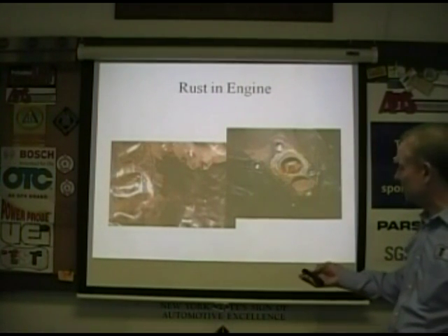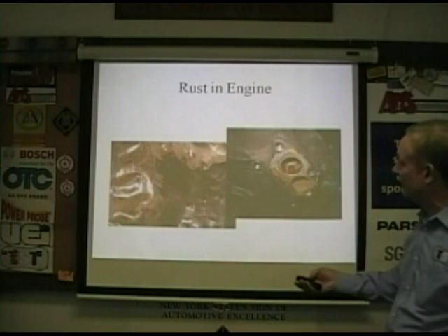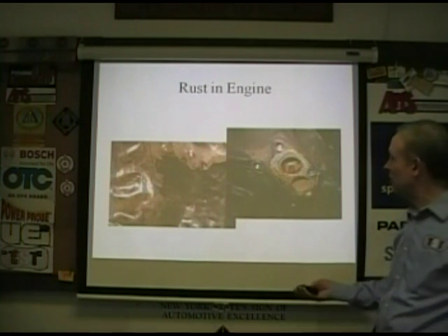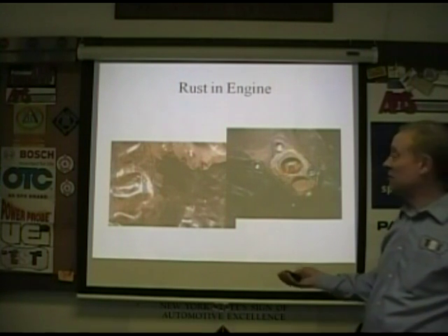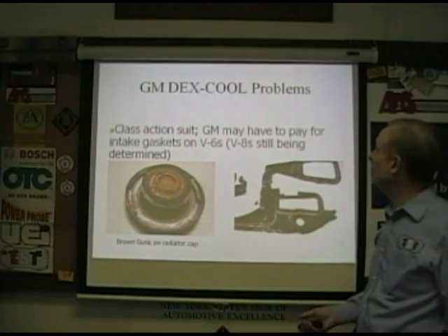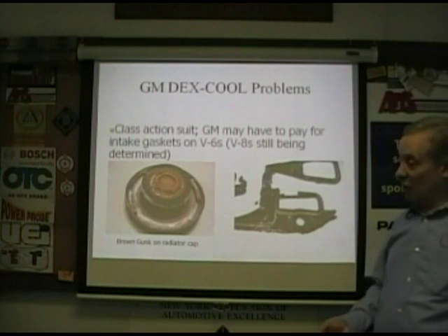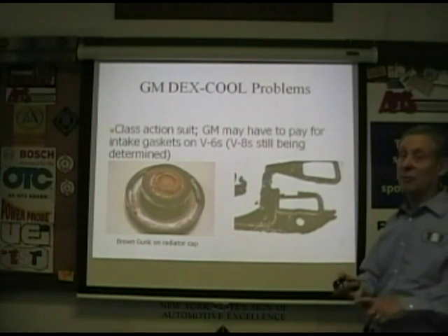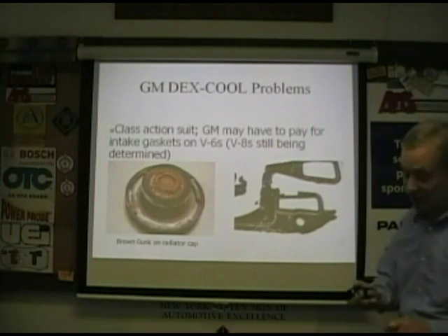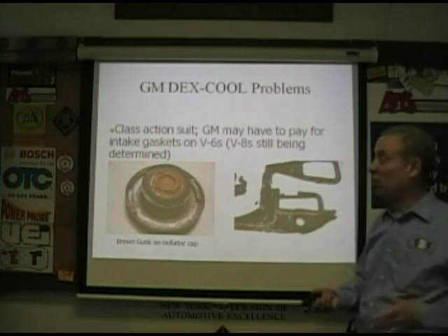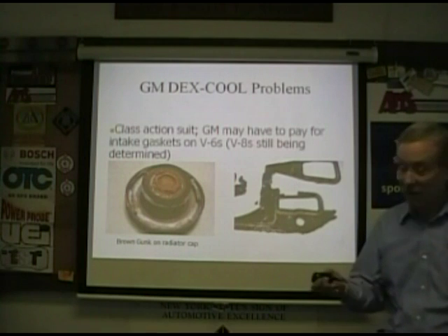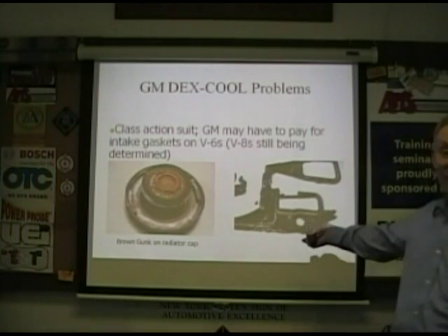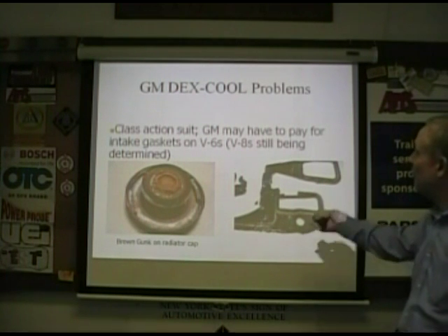Compatibility issue. Rust in the engine, we've all seen this. We don't need to harp on it. Bottom line is, if you see rust in the engine, you know you got a problem with your coolant. You got to flush very aggressively and then put the right stuff in. And probably check those freeze-out plugs. And oh yeah, look for subsequent damage, not just freeze-out plugs. Plastic impellers on water pumps, maybe an overstressed thermostat, freeze-out plugs, damage to a heater core, any of that stuff. Just like you have up there too. There you go. There's a rotted gasket, you know, so forth.